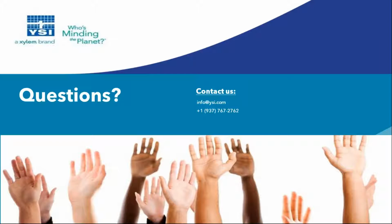There's only one scenario I would find that to be helpful, and this might not be forever. If you're in one of these coastal environments, sometimes we see this, for example, in Monterey Bay in California. They have a need to be measuring, using the Total Algae PE sensor, for some of those marine cyanobacteria, but they also get freshwater cyanobacteria introduced from the rivers that flow into the bay. So sometimes it's useful to use both sensors because you might get a stronger signal on one sensor for one type of algae versus the other.